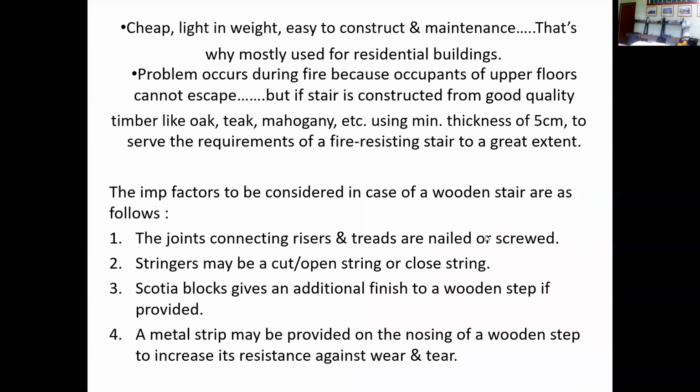So now we have the wooden or timber stairs. This is a cheap type of stairs because it's made of wood. It can easily be constructed and is commonly used in residential buildings. The problem is it's not fire resistant. The joints, the risers and the treads can easily be joined or nailed or attached using screws. Stringers may be open or cut, or strings can be closed.